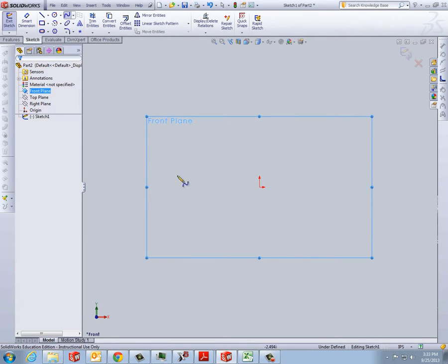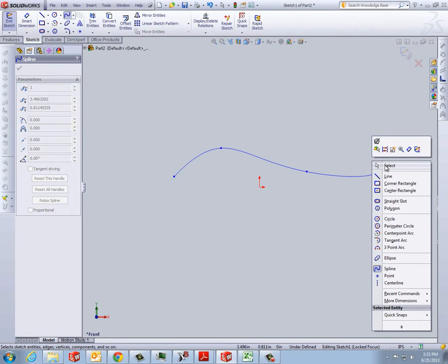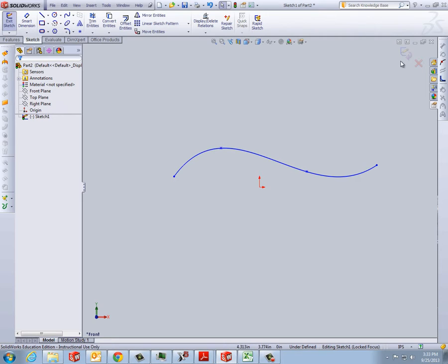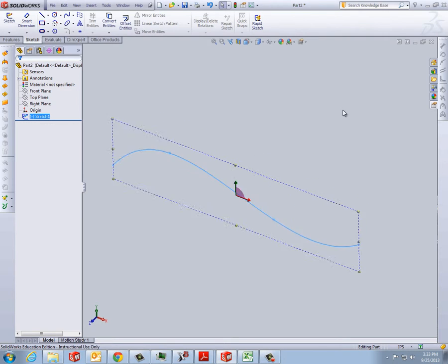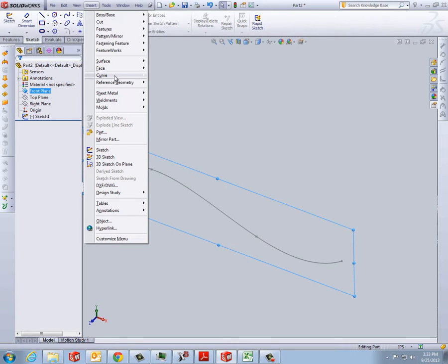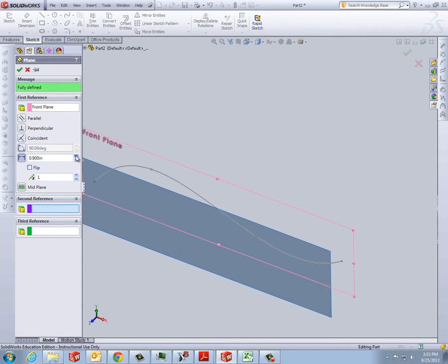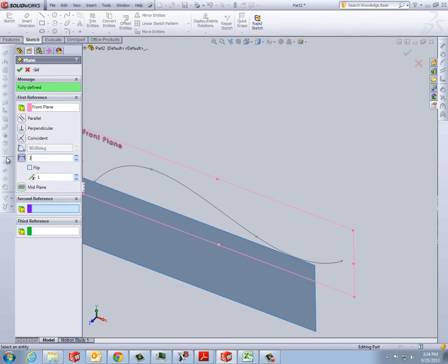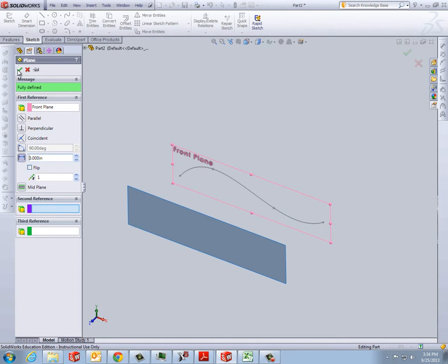and I'm just going to put a spline out here. And agree to this sketch. Now I'm going to select my front plane again. I'm going to insert some reference geometry, a plane, and I'm going to run this plane back 3 inches away from my other plane.